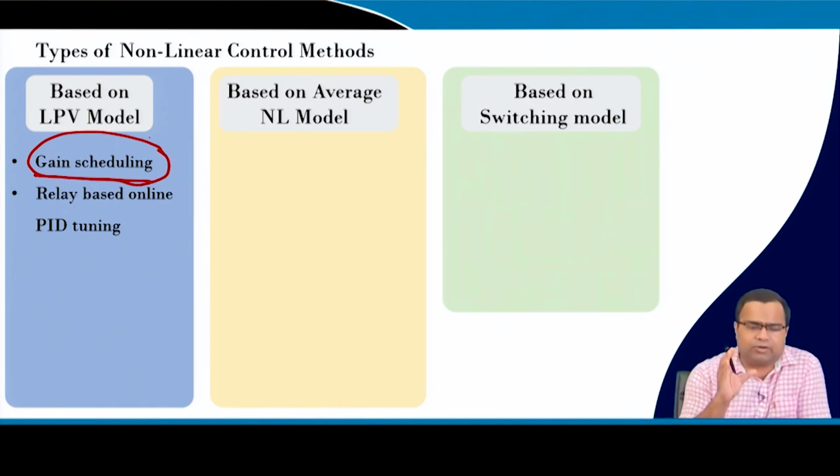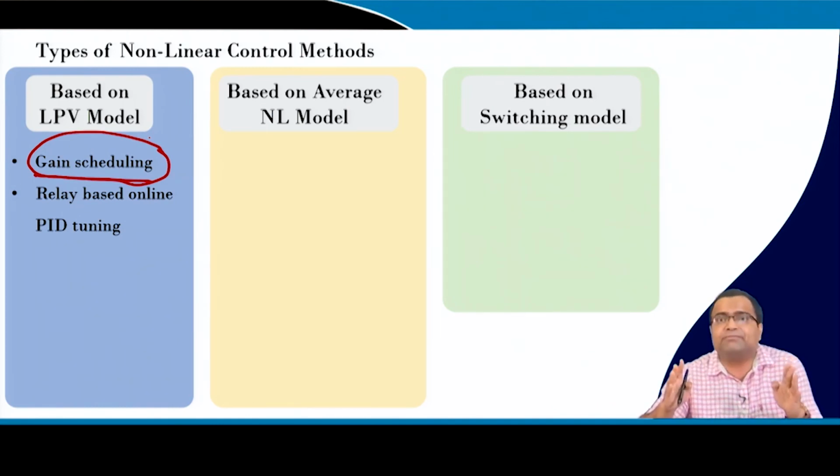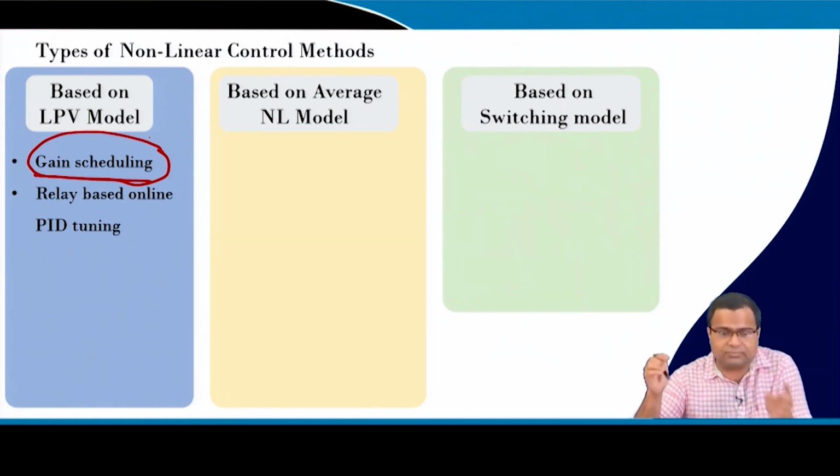We have voltage mode and current mode control, we have taken the small signal model, and we have derived an analytical way of compensator design to achieve a certain crossover frequency and phase margin, and those equations can be used, the parameters we can tune in real time to get a reasonably fast transient for a wide range of operating conditions.